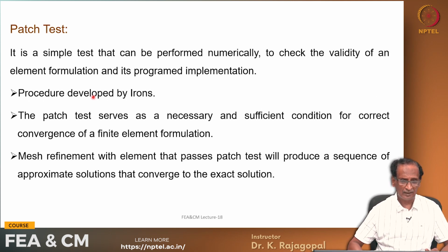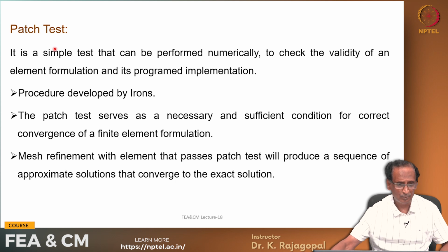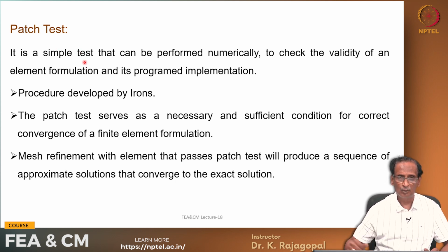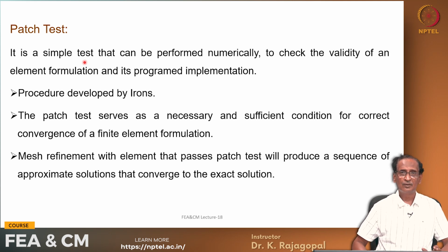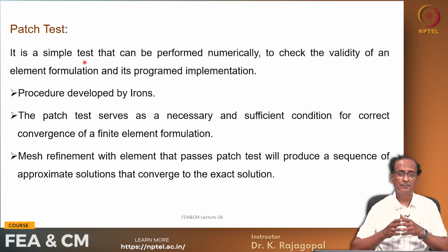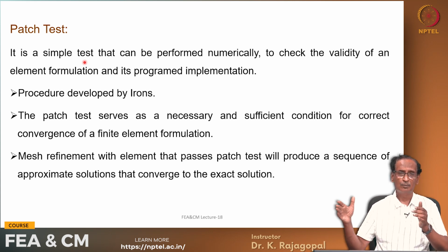And there is one test that is called a patch test, that is performed numerically. We have seen the same test earlier in the context of our generalized coordinate method. We have seen that if you include the constant term, we can simulate the rigid body deformations without developing any strain.